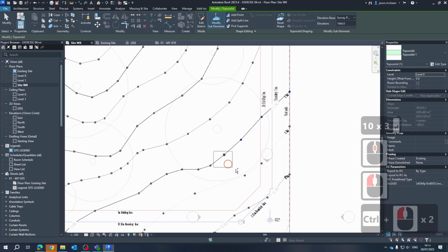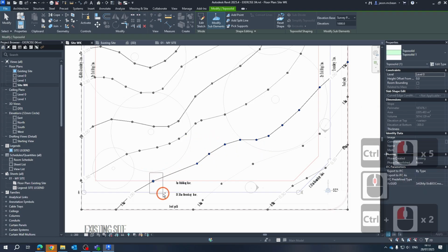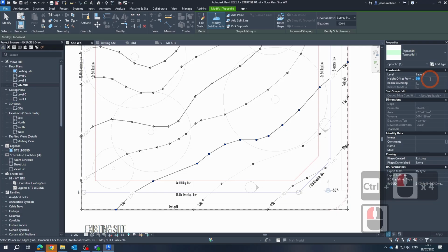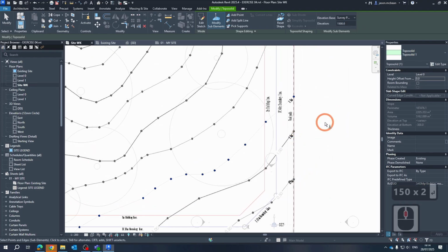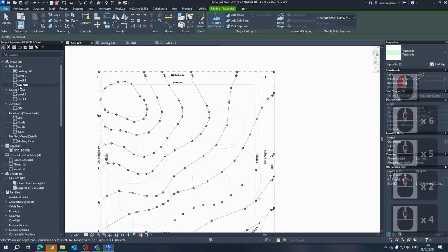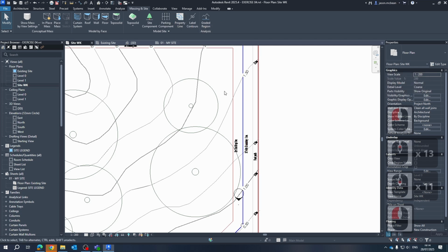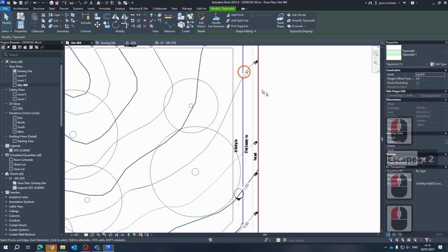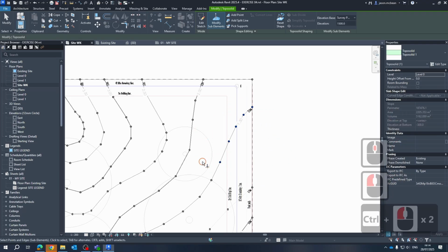So typically, I think what Revit tries to do is read the lowest point and start from there, but it's not typically how we want to do this. It must just take the information provided. Okay, you can see the majors and minors are sorting themselves out. Okay, this is quite annoying. So just make sure, if you're having this error, that you go and correct these points.